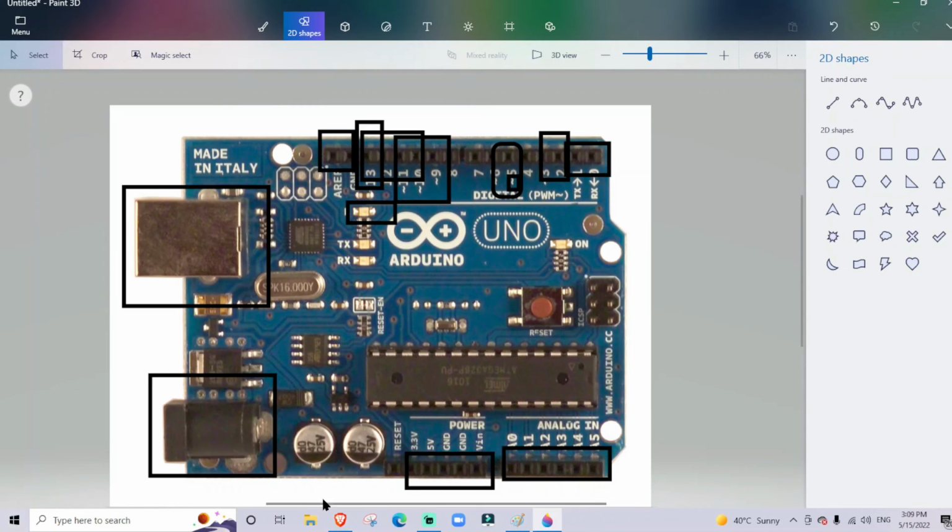So next is the reset pin. Only this is left. Set this to low to reset the microcontroller. This is typically used to add a reset button. This is already a reset button. If we want to add a new reset button, one push button wire will go here and one to GND. This is so simple.